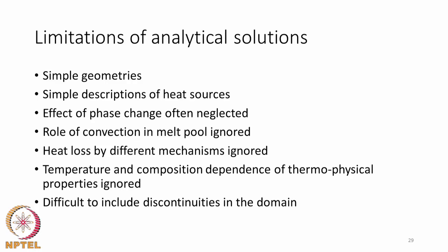The heat sources also fall into only a very small set of simple descriptions. For example, a point heat source, a line heat source, or a Gaussian heat source. So if you are given, for example, a top hat or a downward kind of heat source, then we will not be able to use these expressions. And the effect of phase change has been completely neglected. As we have seen in the formulation, phase change requires a lot of information regarding the melting and the release of latent heat, and all this has been ignored in the analytical expressions.